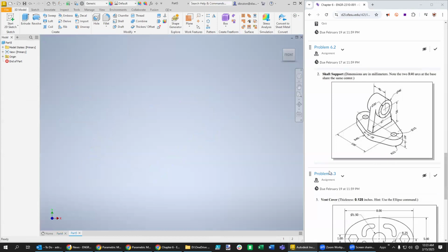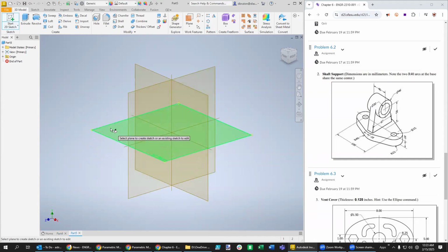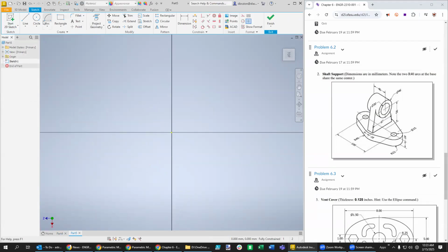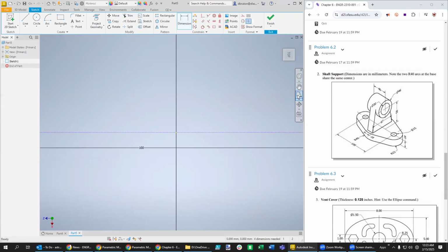And I think the best place to start, obviously, is the base. So this time, let's draw on this surface, which is going to be the XZ plane. And you can see that there's circles out here, one out here, then one out over in this direction also. And they're separated by a distance of 100 millimeters. So we can use a straight line to connect them. And then, of course, make that line a hidden line. Can set the dimension of that to be 100 and then rescale back down like so.